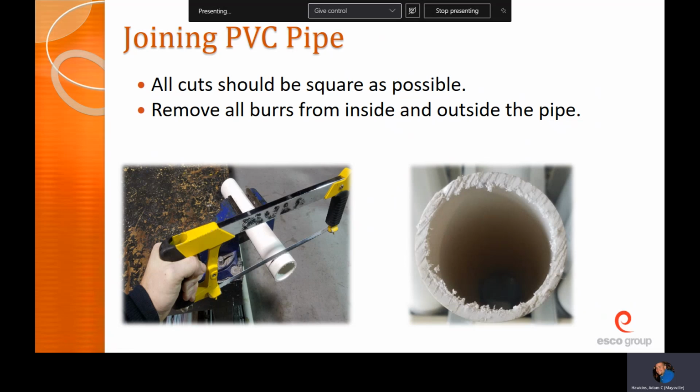Most of them come with a 2-inch opening, but you may have to upsize to 3-inch pipe because of static pressure buildup in the pipe. So you're really going to want to refer to manufacturer specs on how far you can pipe with 2-inch pipe. If you go very far, you're going to build up back pressure in that pipe because of friction, and it's going to cause your pressure switch not to work right over time. It could cause your furnace not to run all the time.